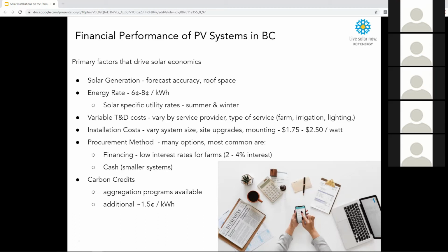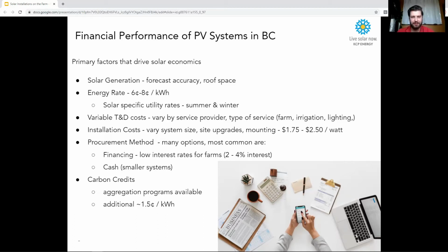On farms, it's pretty rare that there's not some available space we can find for some panels. The other thing when you're trying to site where you want to put it is to put it as close as possible to where you're able to connect into the electrical system, because the further away you are, the more wire you're going to require, and the more it'll cost.